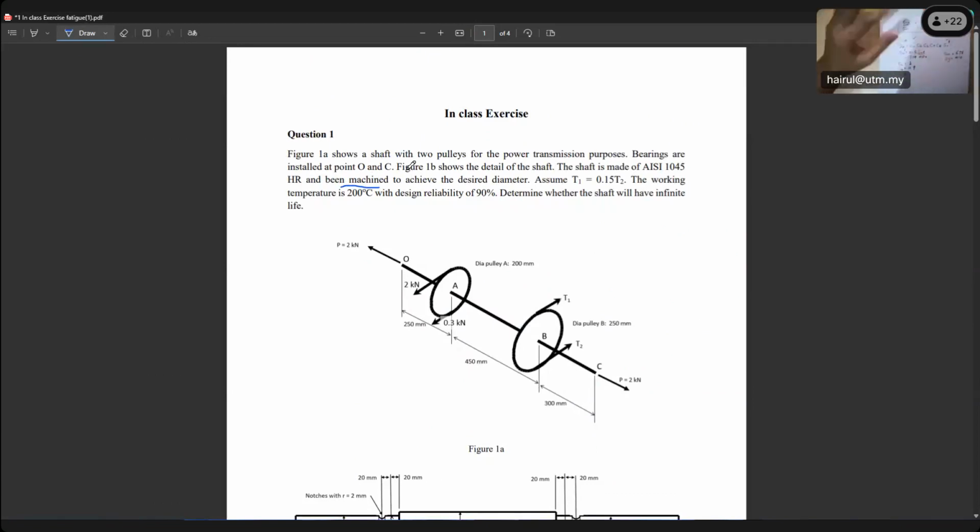No, not necessarily. Just lathe machine. When you do a shaft and you are turning on the lathe, that is machining. It is not polish, it is not grinding, just turning. It said normally machined. But be careful, sometimes the question does extra things. Sometimes it says the surface is fully ground, fully polished, something like that. But this is just machined. Surface finish of your shaft.